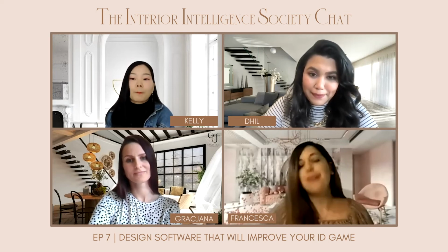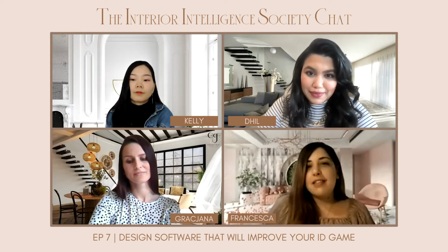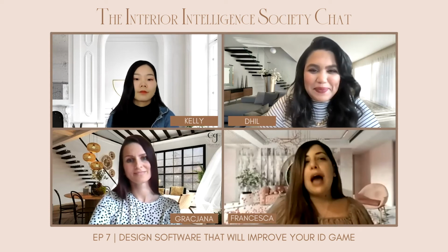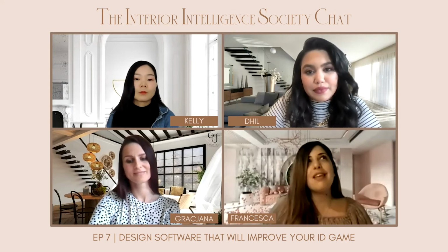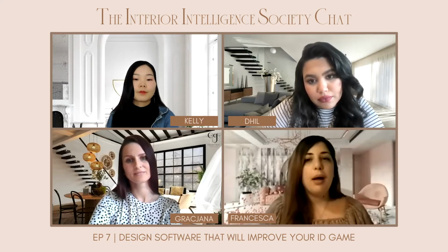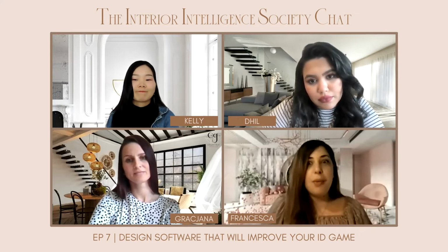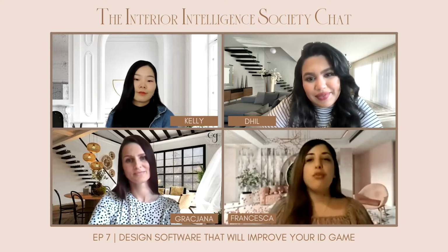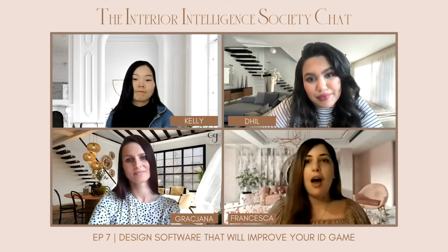The last but not the least is SketchUp, because it's so easy. But even if it's so easy, for me it was difficult in the beginning, because for example, for me it was impossible to make a sphere, because on SketchUp you don't have a sphere button, so you have to create the sphere with the line tool.